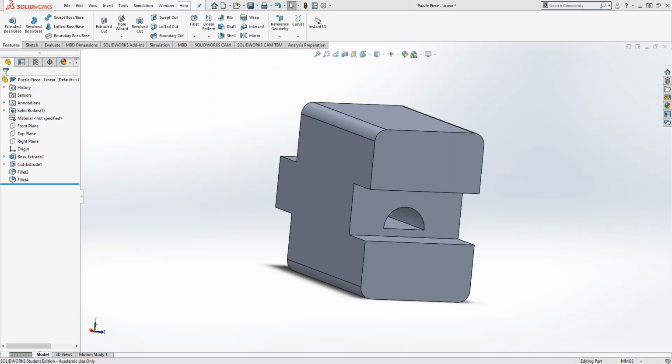But now that I have this shape, I can go ahead and go through to the features menu again, and I can make an extruded cut. Now here's the interesting part. You can see right now the outline of this shape. It's going to basically just extrude and cut away, delete all that material from the sketch that we have on that front surface.